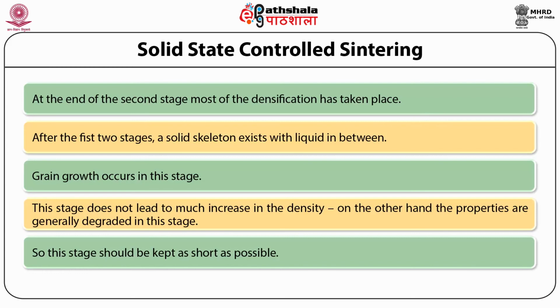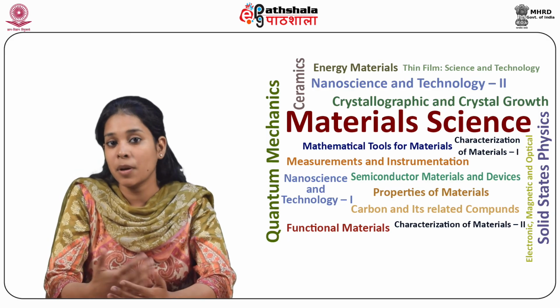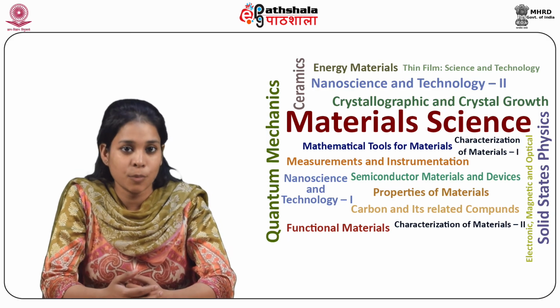It should be, however, pointed out that a trace amount of a liquid phase is invariably present even in the high purity ceramic due to siliceous and other impurities. For example, in silicon nitride, a few angstrom thick layer of yttria silica film is found to be always present at the grain boundaries.